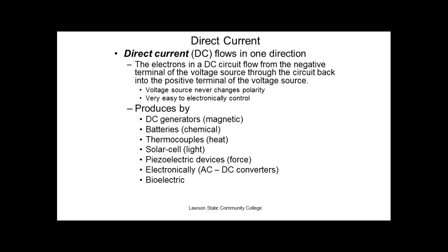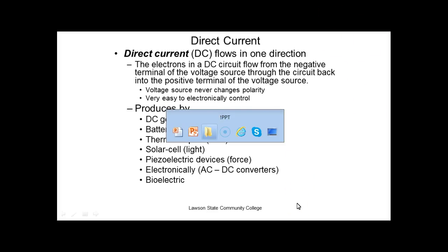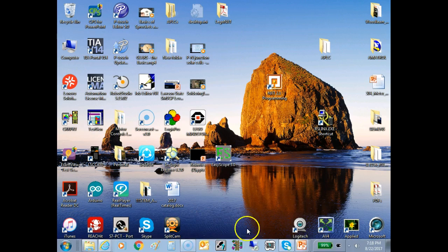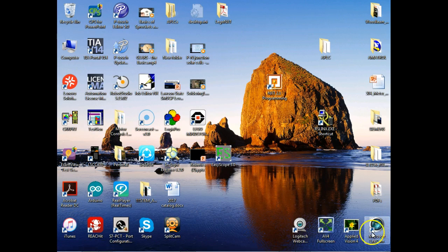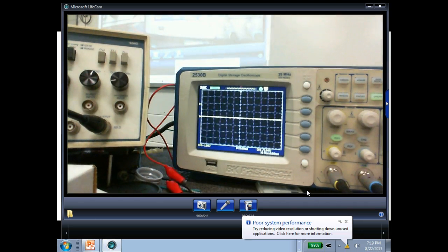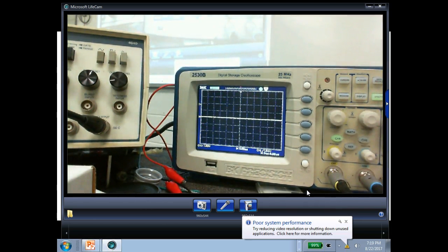I can show you this on the oscilloscope. I can show you me. I'll show you all that later. An oscilloscope has a really high input impedance, so it doesn't load down signals a lot like your meter does. So normally what we can do is we can literally touch the end of a scope probe as soon as it pops up. Hopefully it's connected. Okay, so this is an oscilloscope.